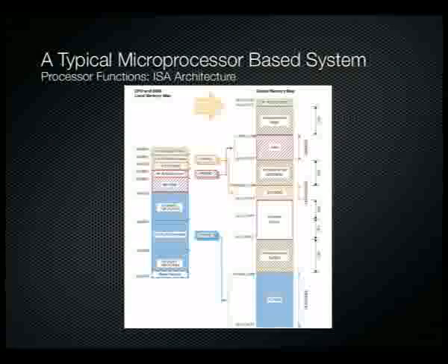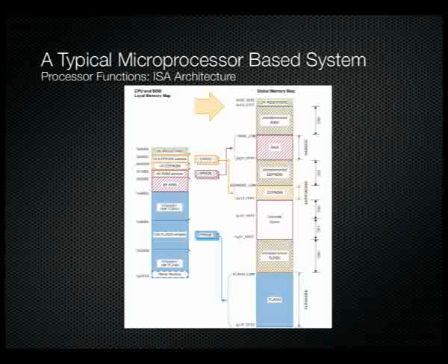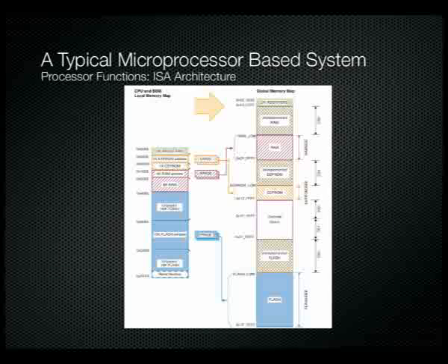And I've shown that here in this diagram. On the left, we have our linear memory map from 0 down to FFFF, and inside that linear map we have our various windows for our RAM, windows for our EEPROM, and windows for our flash. Therefore we can see the segmented memory map on the right, a very segmented memory map where we can point our windows to the various pages inside that segmented global memory map.